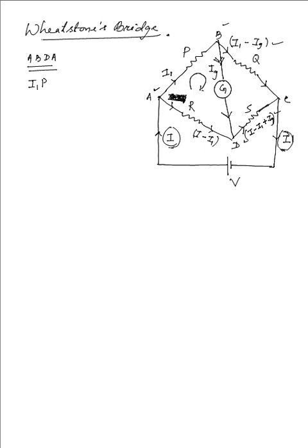So, as I had taken previously, it is positive, that is I1 into the resistance P. Again, as we move from B to D, VB minus VD, we have the current Ig, which is obviously along our sense, so this will be positive as well. So Ig multiplied with G, the resistance of the galvanometer, as I had said earlier.